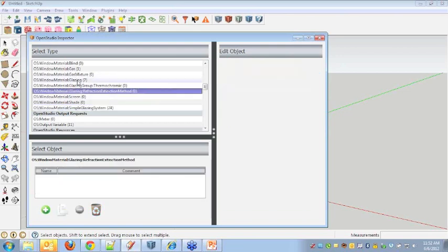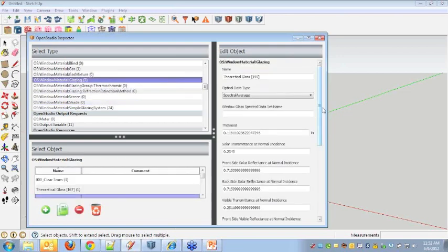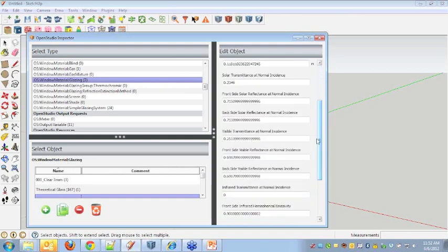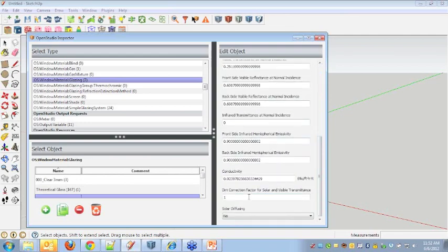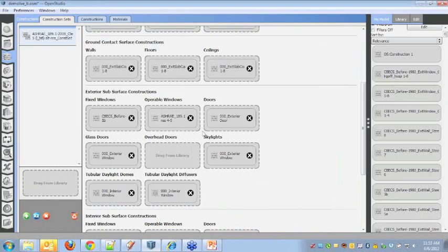So you can just set those three values and then use that window. Energy Plus also has a far more advanced construction that has a lot more inputs. So you have a lot of inputs related to the reflectance and transmittance from front side, back side, and then conductivity and then a number of things. So anyway, you can use either of those, and I believe Energy Plus has a number of additional ones. These are just the two that our templates are preloaded with, depending upon what vintage you're using. So if you don't want to use the building component library, you could just edit your U value of your window manually within the SketchUp plugin.